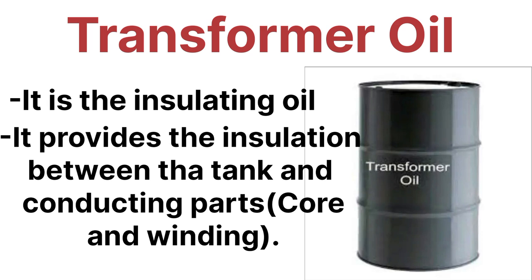Okay, so it is insulating oil, and it is oil that is stable at high temperatures and has excellent electrical insulating properties. So these are the properties of a transformer oil. Generally it is used in oil filled transformers, and sometimes we use it in high voltage capacitors. Fluorescent lamps also use the transformer oil, and sometimes high voltage switches, because it is generally used as an insulator. So that's why we are using it in that case.